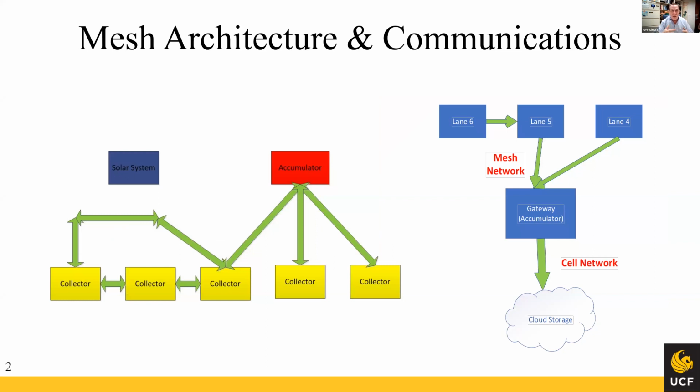So what we settled on was mesh networks operating on microcontrollers. The beauty of mesh networks is that, unlike traditional communications, each node can first try to communicate with the closest node, and the architecture of the network can heal itself if one or more of the nodes, within reason, of course, stops operating or communicating. So we settled on a microcontroller architecture, extremely low power, operating on a mesh network. We did not go to things like Wi-Fi, LoRa, and Bluetooth because their power requirements are a little bit higher, and there are some limitations as to how quickly the network can heal itself if we need to.